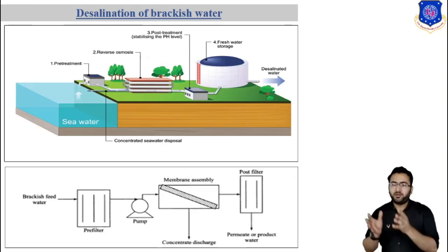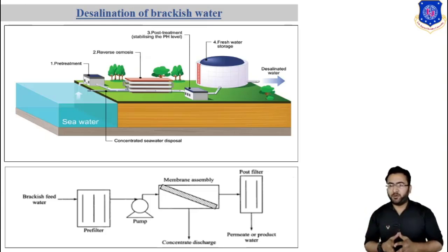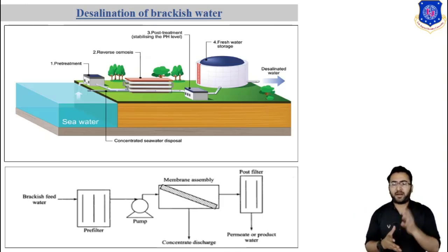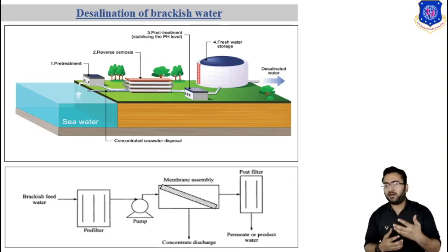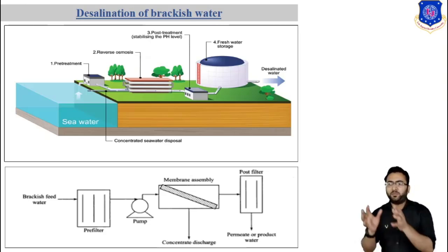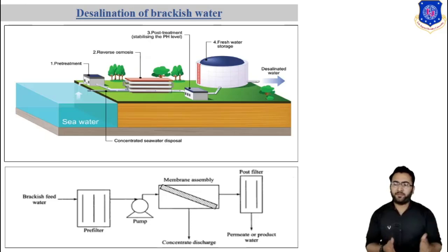As such, solids in the water must be removed, and the water is given treatment to prevent salt precipitation and bacterial growth on the membrane. The pump supplies the pressure needed to push the water through the membrane, while the membrane rejects the passage of salt through it.